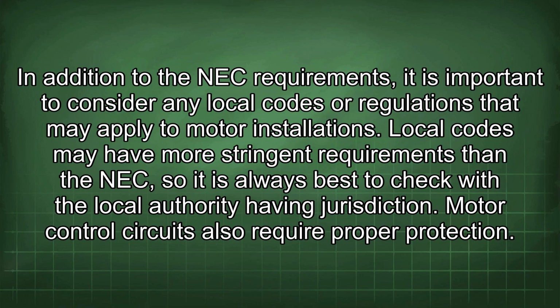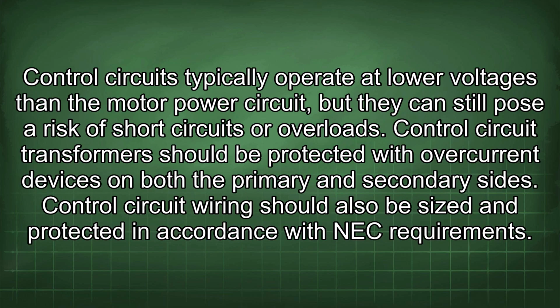Motor control circuits also require proper protection. Control circuits typically operate at lower voltages than the motor power circuit, but they can still pose a risk of short circuits or overloads. Control circuit transformers should be protected with overcurrent devices on both the primary and secondary sides. Control circuit wiring should also be sized and protected in accordance with NEC requirements.